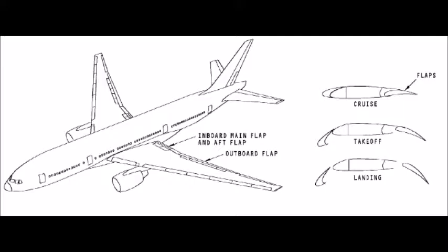When the flaps extend, they increase the lift of the wing. They also help to decrease the airspeed during landings and approaches. The flaps are part of the high lift control system. The high lift control system electrically controls the flaps with a fly-by-wire system. During takeoff and landing, the pilots use the flap lever to command the flaps to move to an extend position. During cruise, the pilots command the flaps to retract to the up position.